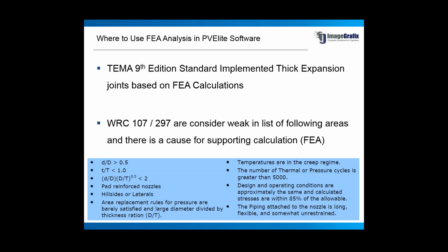So that's the point which we are trying to highlight in this place. Apart from this, there are a few things which are pretty straightforward, like the pad reinforced nozzles. If you have reinforced pad nozzles used in your system, then obviously the WRC is not going to address the same. So you need to go for an FE analysis.